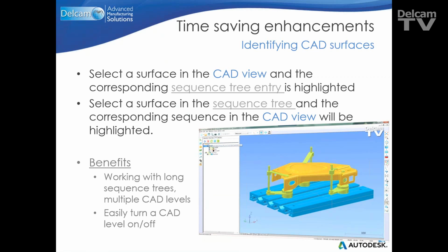This is also available when using existing CAD levels as well as user-defined levels. As you can see, we're clicking on our levels and then lastly the user-defined level to select them all. By clicking on the I button in the CAD pane, we switch between a detailed and a summary view.